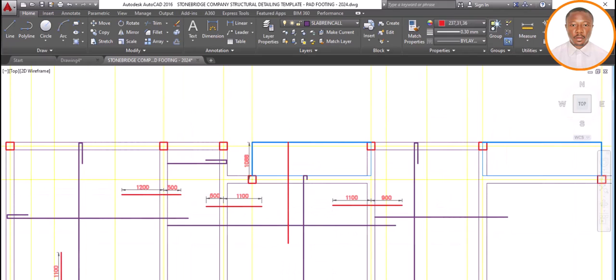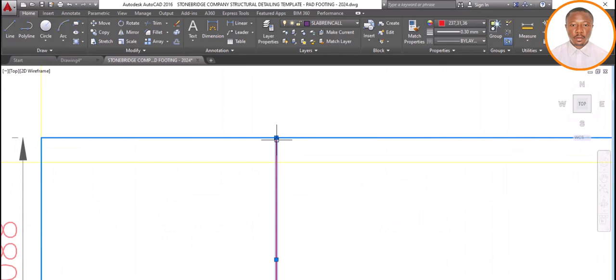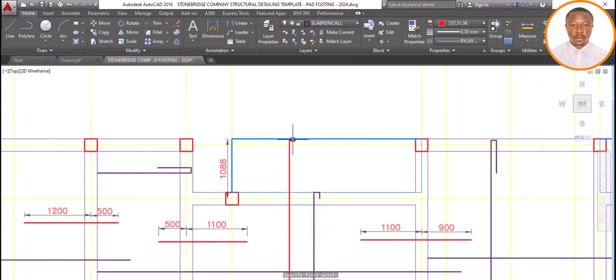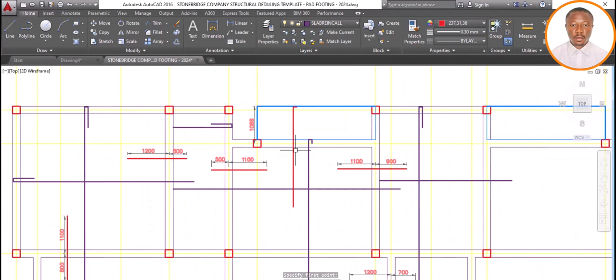So this is what we are going to have as our top reinforcement. This is what we're going to have at site in order to design. And this becomes my member. Then we can remove our concrete cover, which is 25. Enter. Then 25. Enter. Have our reinforcement of, let's say, 100. Yes, 100. Then I have this. This becomes my top reinforcement. So do we get it now?